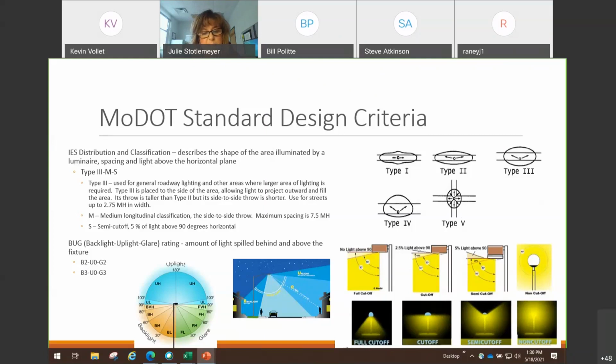You can kind of see the spectrum of where those fall. So what they do is they do testing on all their point sources, kind of using the circle of light, and they measure where these lights fall. So for the B rating, they have these 3 areas of light they will measure. They try to keep not as much light in the BL or the BH and put all of it into the BM kind of area. And then they come up with these ratings.